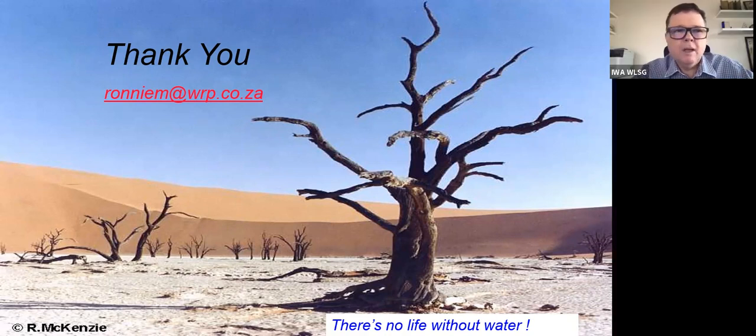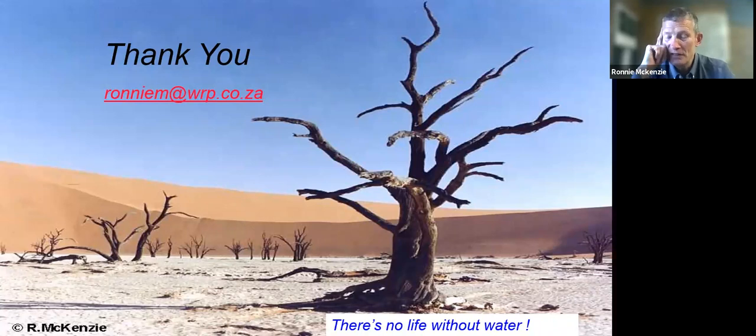Okay, we've got a question from Ian, which is, as PRVs are a potential source of pressure transients, what are people's views on monitoring the PRV outlet pressure for pressure transients using high rate pressure transient RTUs or data loggers? Okay, I've heard about this being done. We haven't done it ourselves. I know that there's a number of companies that specialize in these microsecond loggings where you try and pick up transients in pipes.